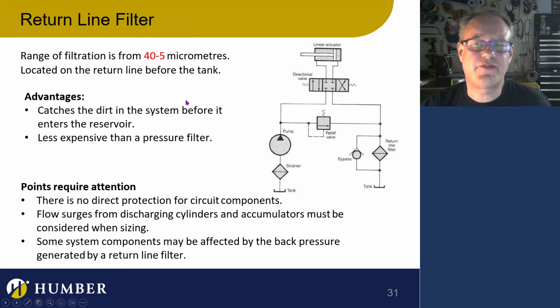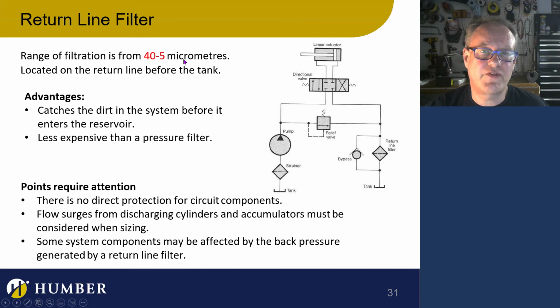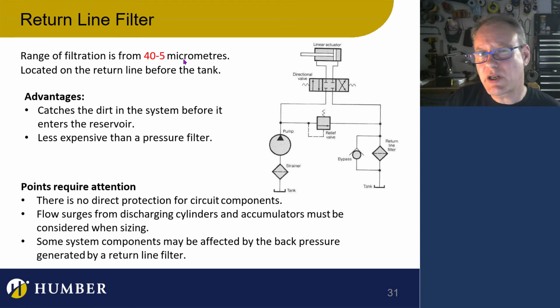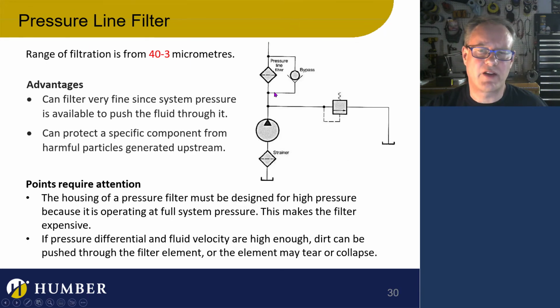Cool. Our return line filters are going to be down here as well. There's also going to be a bypass on the return line filter, because if it gets blocked for whatever reason, you're going to want to make sure that the fluid can get past it. Now, these guys don't filter out as well because they're not under pressure, but they can be under pressure. Hopefully this makes sense. If I go up here to the pressure line filter, this is definitely under pressure. The pump is pushing fluid through there with a lot of force.